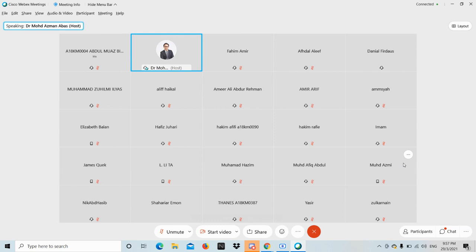But engines nowadays are clever enough to detect knocking. If there's any knocking, the engine management system should be clever enough to make changes to the ignition timing to prevent knocking and mitigate the knock events. But their actions are limited. If there's slight knocking, definitely it can be prevented by the management system.